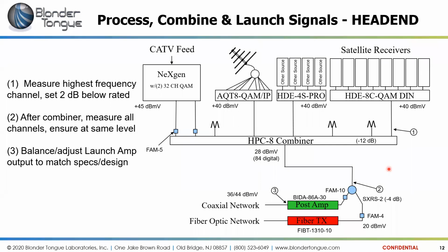But when you're combining externally, combining different things, especially if they're single channel devices, it is advisable to run them in non-adjacent ports for adjacent channels. So if I had, say, channels 2 through 30 here and 31 through 60 here, I would be better off if I took this connection and moved it over physically one spot on my combiner to offer better isolation between the two outputs. Yes, that is correct.